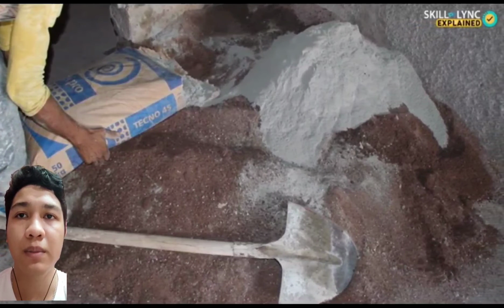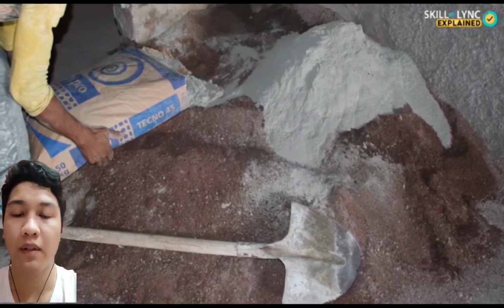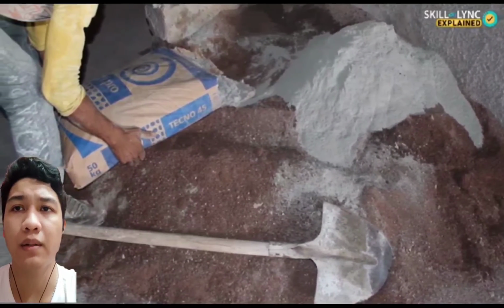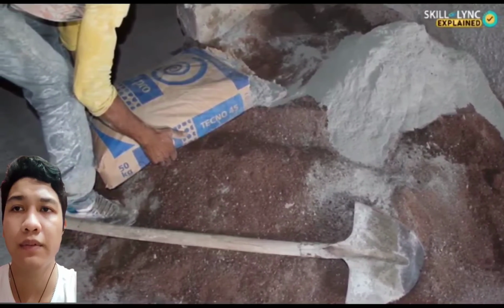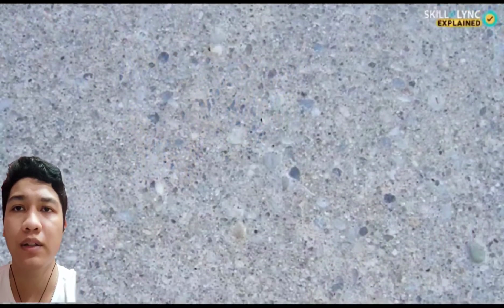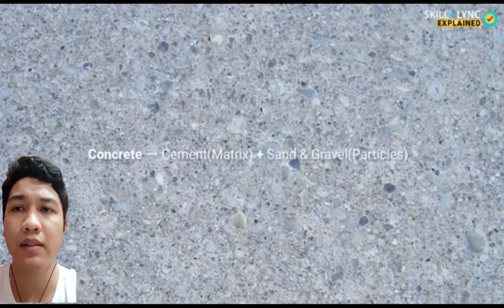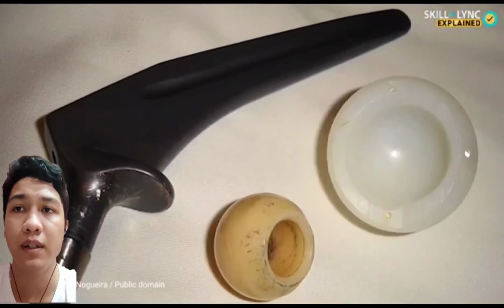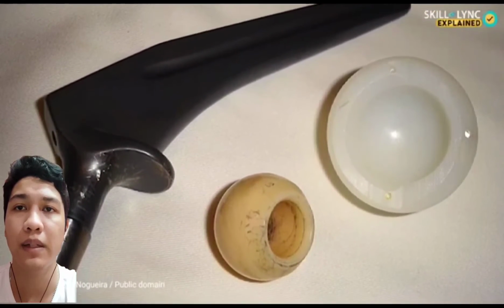In large particle composites, the interaction between the phases should be treated at the continuum level. Here, the filler material replaces some volume of the material and modifies its property. The change in property depends on the volume of the filler material. Concrete is a very good example of this type. Here, cement acts as the matrix and sand and gravel act as the particles. Another example of this type is cermets, which are composites made of ceramics and metals.